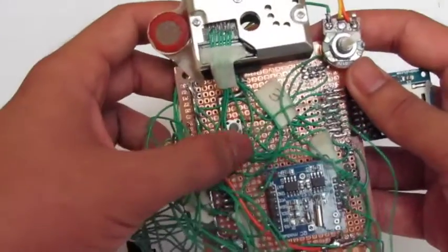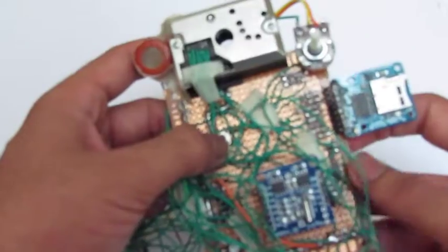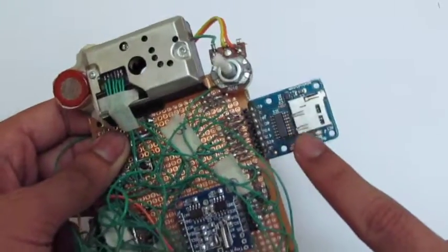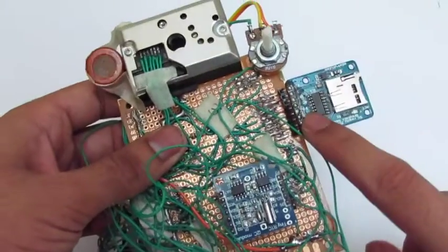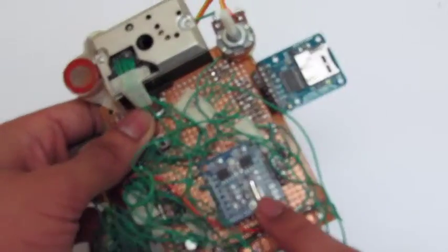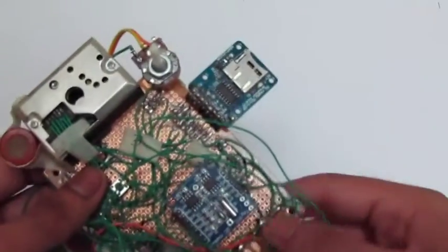You can also see a small push button here, as the client requested. When the push button is pressed, the Arduino should start recording all the data on the SD card, and when it is pressed again, it should stop recording. And while all these recordings are taking place, it should fetch the time from the real-time clock and store it in a separate array next to all of the other data.